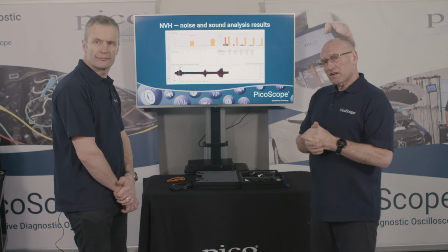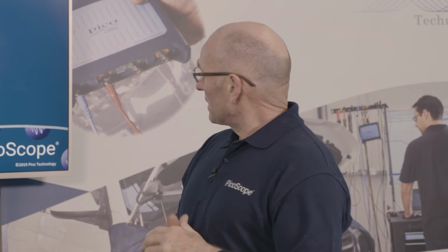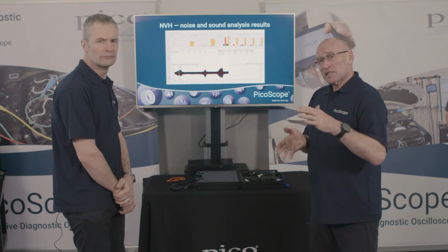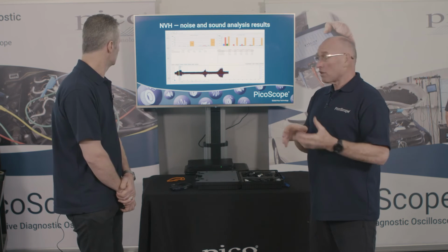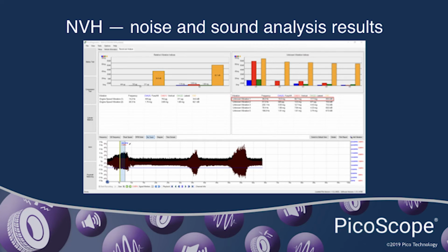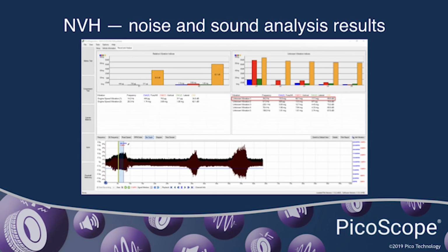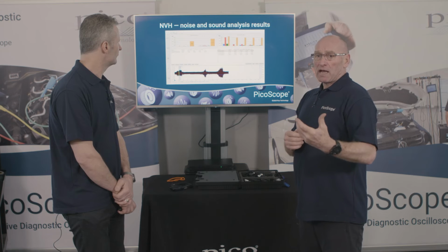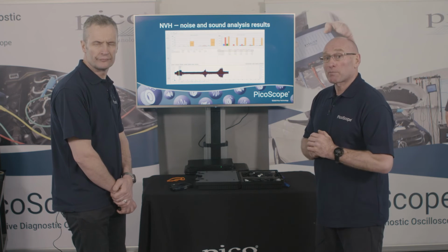I think the really interesting thing I've picked up from this bar graph is that we can clearly see on the right-hand side that this frequency of around 35 Hertz sits quite nicely between E1 and E2, so we know it's not the engine. I think the way I'm thinking at the moment is, if we increase the frequency of the engine, there could be a situation where we get resonance, where we get two forces out of balance which add together. But looking at it in this way, we're able to separate this issue and see very clearly that this is a non-engine related component causing this problem.